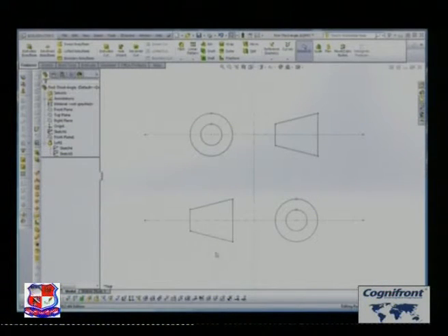In regard to projections, for the third angle projection, think of this as a fold line, and the same for the first angle projection. In the third angle projection, you're folding this part down, and that turns into the right view. It will always be the right view, whether it's first angle or third angle. It just depends on where you put it. But this is the right view, and if you fold that down, you can see how that works.